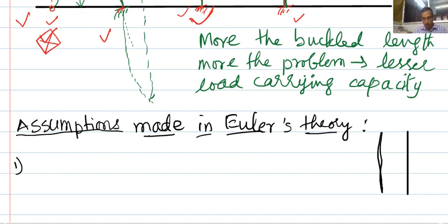See, the way I draw, I am not able to draw straight. Practically, people can make it straight, but when it comes to the side, there will be slight tilting. That may be because of so many practical situations. If you take steel columns, people bring them in trailers and throw them from the trailers on the ground, because of which there will be a little bend, then this theory will not work for this kind of column.